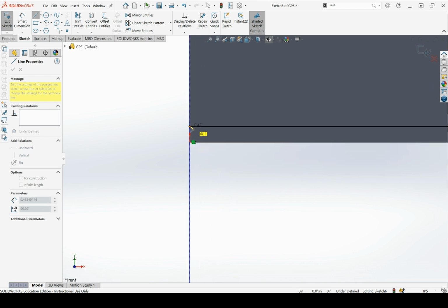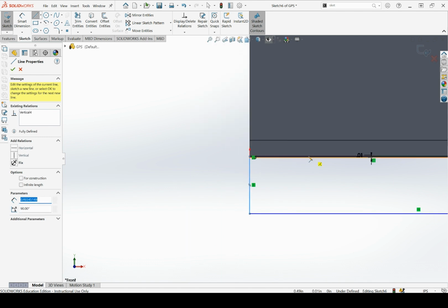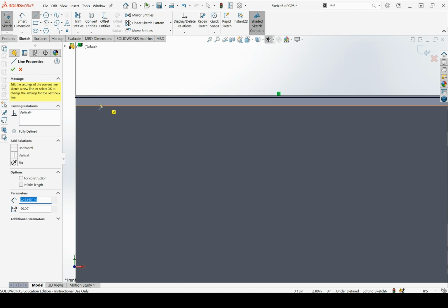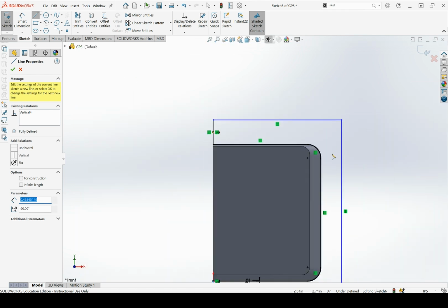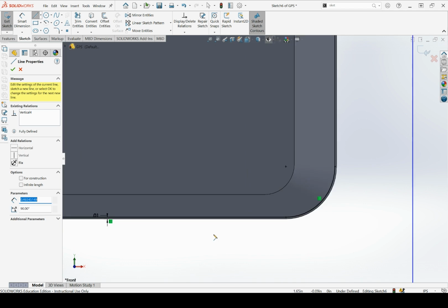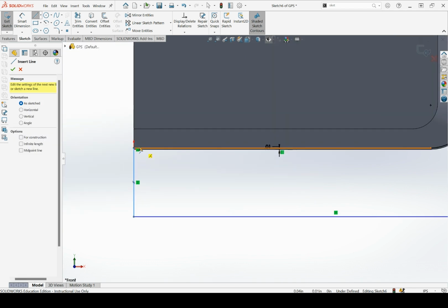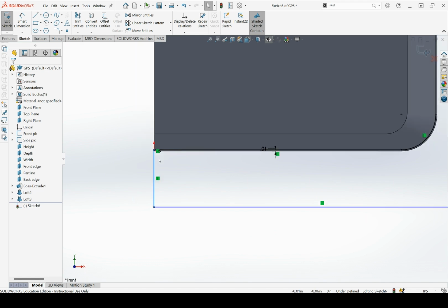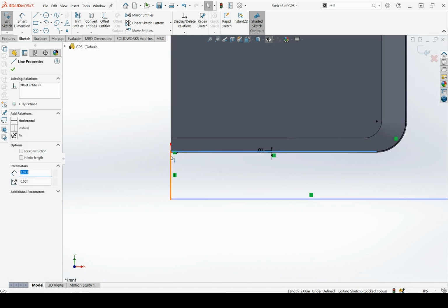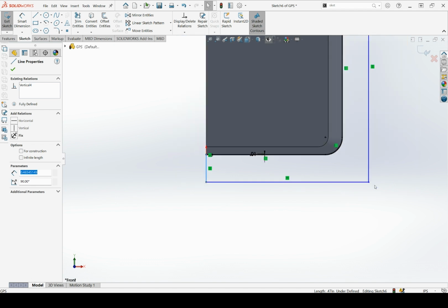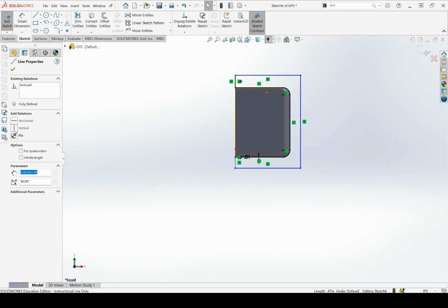I want to connect to this black line, on this dot, because the black line was part of my sketch. So my sketch should be connected up here to this part, and it should be connected down here. If it's not connected, that's going to cause me problems later. So I should have this whole sketch, where part of the lines are black, that was my offset entities, and part of the lines are blue.